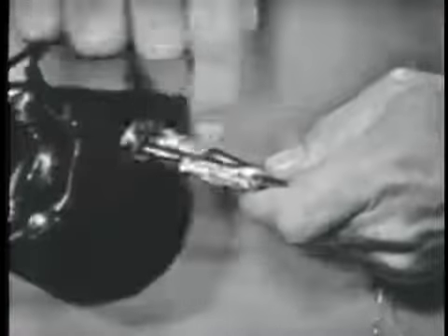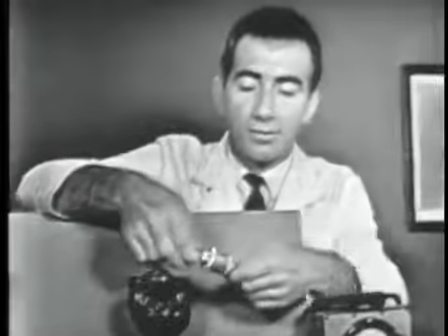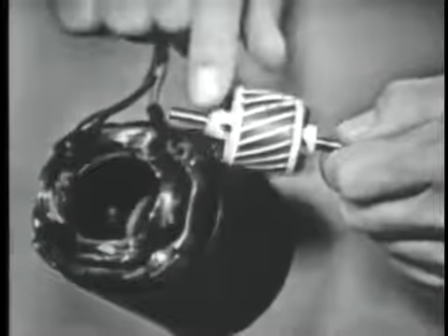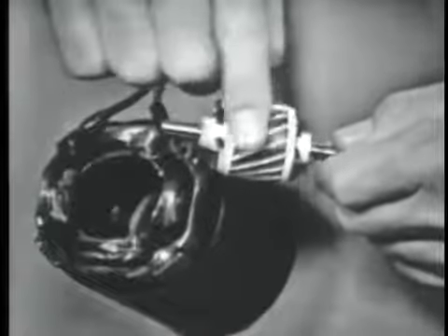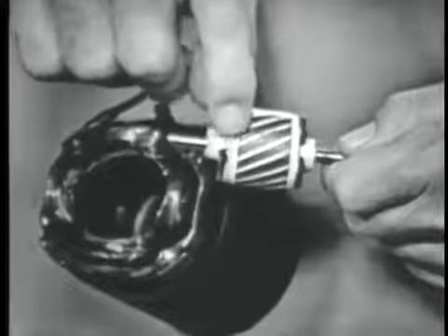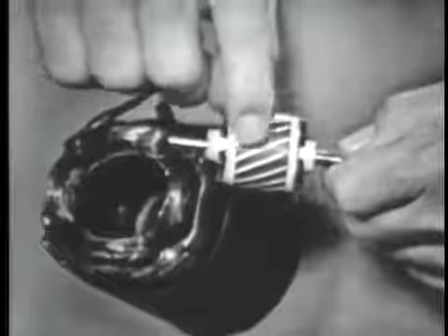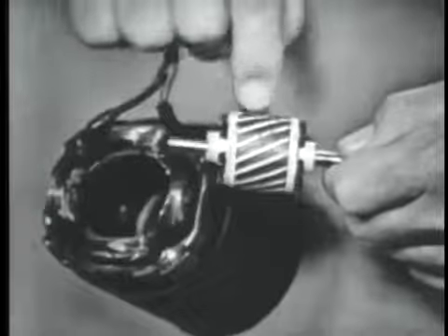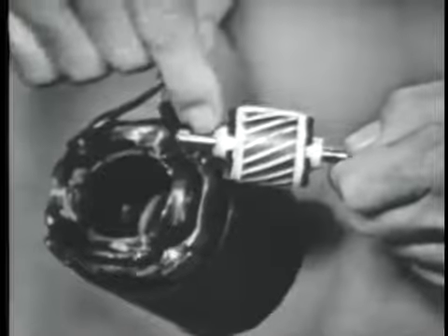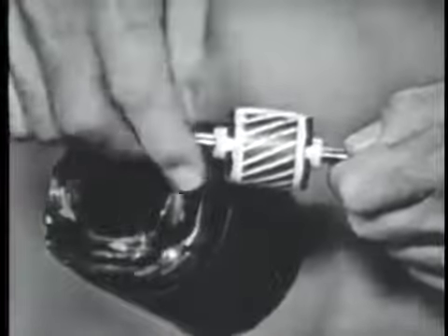An electromagnet, right. Now actually, the rotor is the same thing, or almost the same thing. And a rotor is made in a very, very similar way. Instead of using windings of wire, however, we use conducting ring on this end, conducting ring on this end, and they're joined together by conducting bars, these little white lines. And the reason I say conducting, sometimes they're made of copper, sometimes aluminum. This one happens to be aluminum.